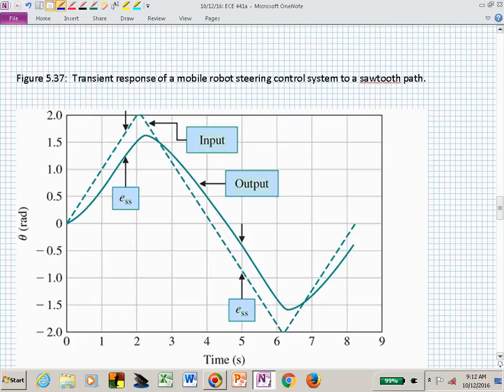And the steady state error is defined once you've reached or settled, or once you've passed really your settling time. Here is where an infinite amount of time isn't very long, you hope. Right? How long is infinity? 5 tau, 5 time constants. So if your tau was a millisecond, infinity now is 5 milliseconds. After 5 milliseconds, you're now at steady state.